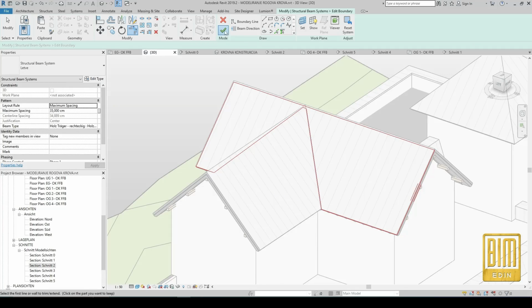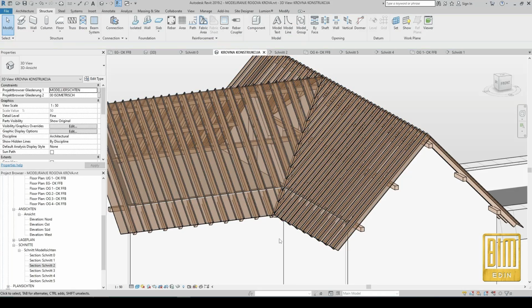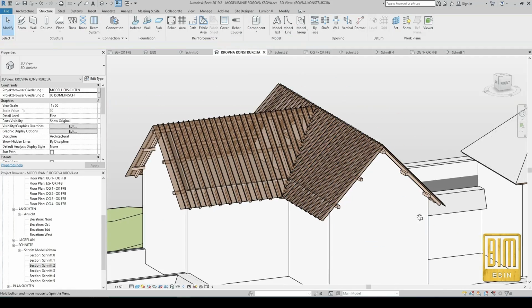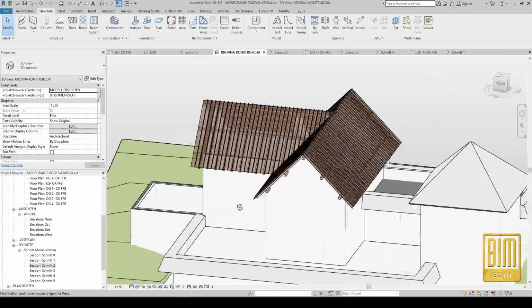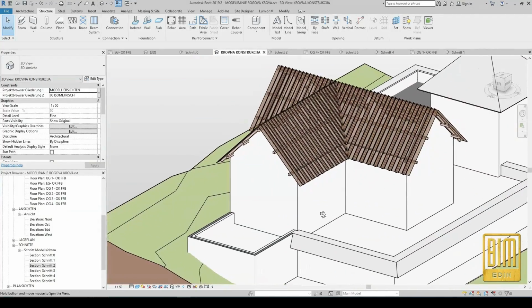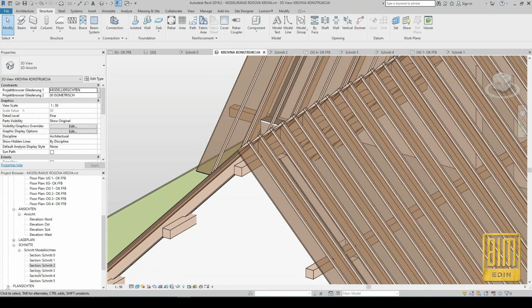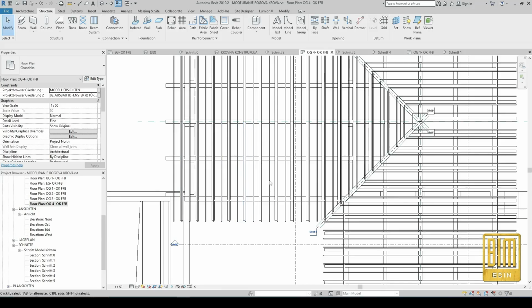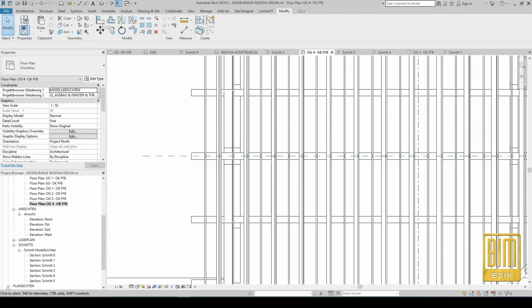Alright, when we finish this, you can in a very easy way calculate all quantities of the battens and counterbattens. You can even calculate the count of the battens. Some manufacturers sell the battens by number. You can calculate them by volume or by numbers using very simple formulas.